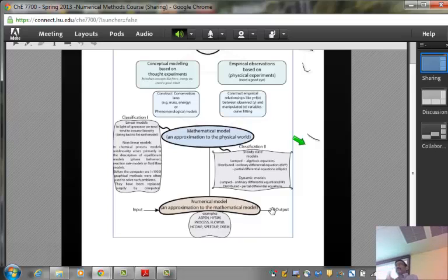Based on that, I take my reaction kinetic data, and then I want to design a large reactor, 10,000 liters, because I want to produce more of that particular chemical for which there is a market. Then the question is, is that large reactor going to behave in the same way as a small reactor in terms of the spatial variation? If I take a sample near the inlet or near the outlet, are they going to be different? So how do I maintain the same condition that I had in the lab?